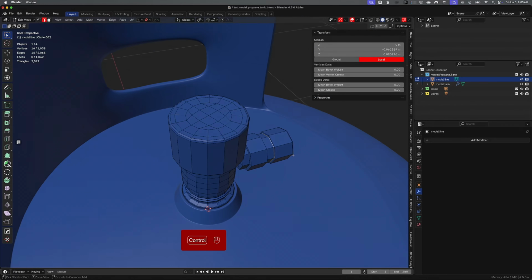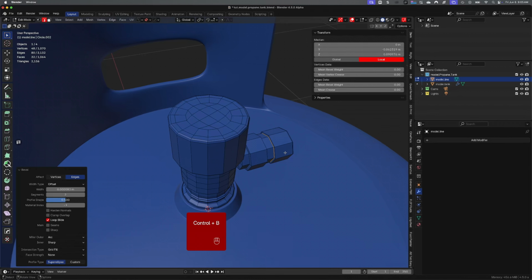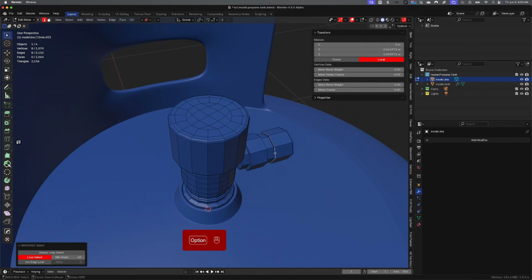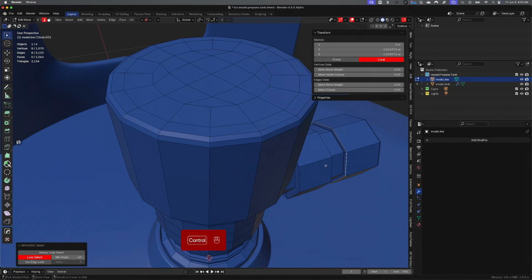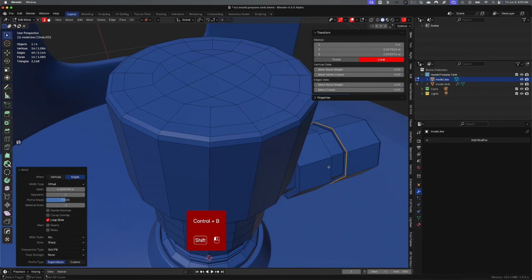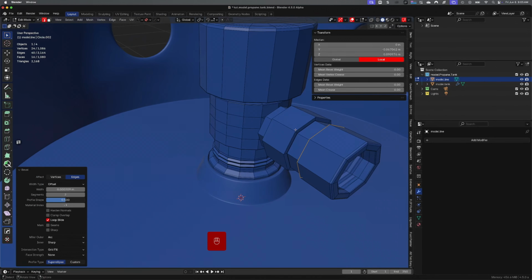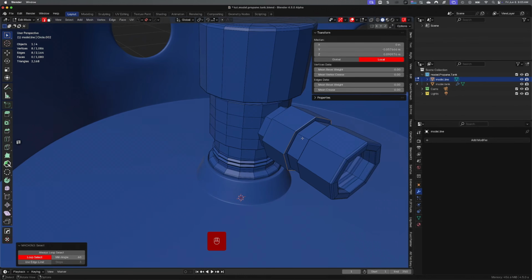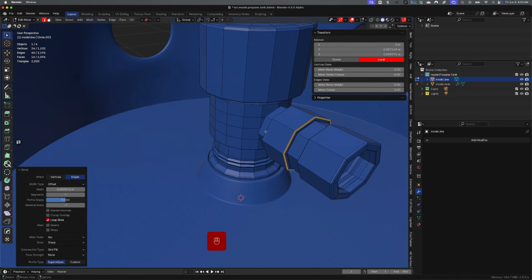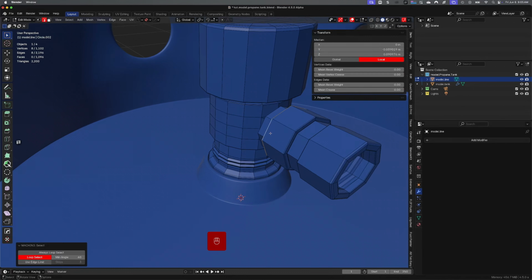And I'm just coming here and I'm selecting these edges that kind of were part of the extruding and sizing piece, where we take one shape and then we bring it out and make it a little bit bigger, and then we extrude from that. These little stepwise pieces, I'm taking those and tightening those up, so when we run that sub D on them, we don't lose the shape. We don't have a big giant blob of stuff there.